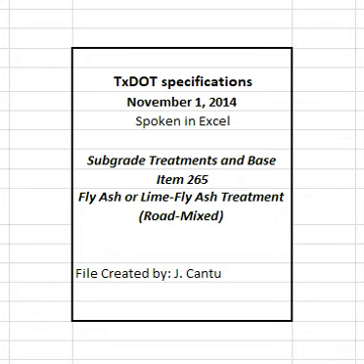4.4.1 Ordinary Compaction. Roll with approved compaction equipment as directed. Correct irregularities, depressions, and weak spots immediately by scarifying the areas affected, adding or removing treated material as required, reshaping, and recompacting.